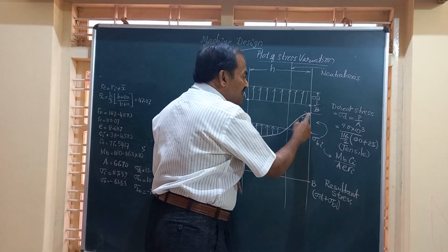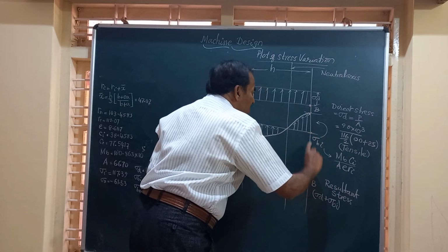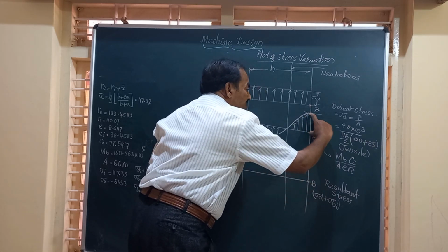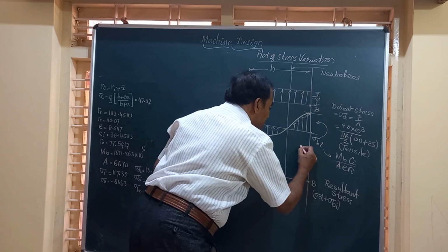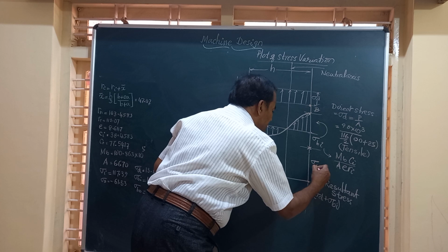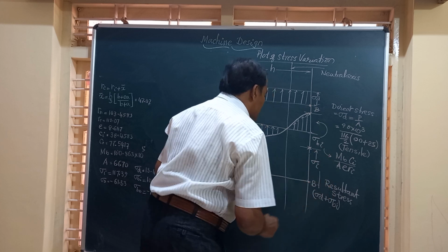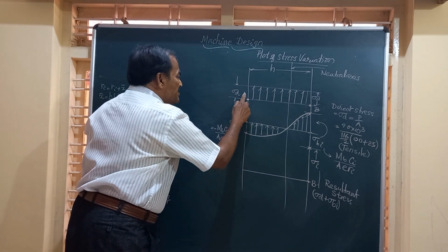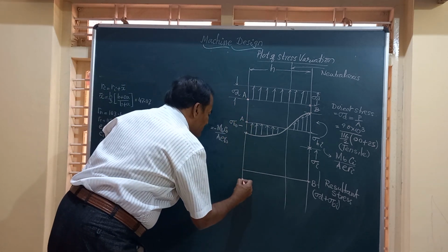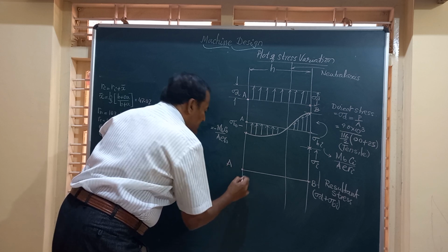So both are positive, and hence I am going to mark a height here which is the summation of this height plus this height. So it is going to be something like this, this is our sigma i, the resultant stress on the inner fiber. Similarly friends, here this is negative, this is positive, the difference will be the resultant stress at the outer fiber A.